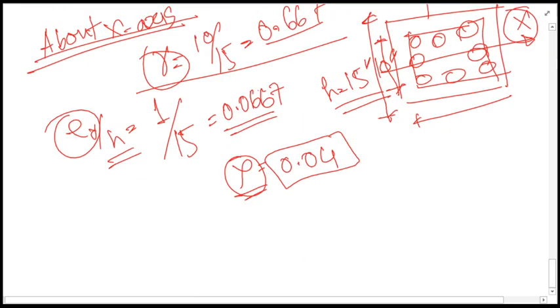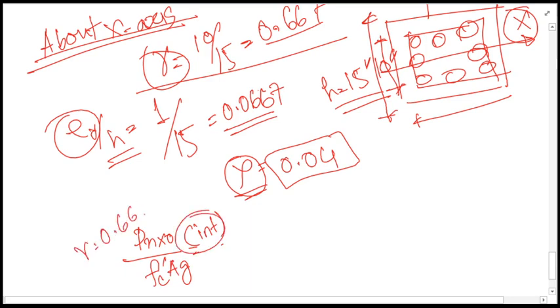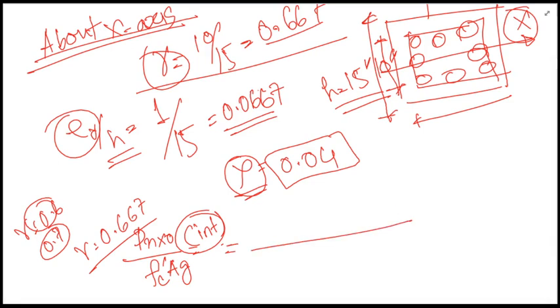Now we'll be calculating, using these two, the capacity in the x-axis, that is Pnxo divided by Fc prime Ag. You will be getting it from the similar chart. We'll be again interpolating this to get gamma equals 0.667, as we don't have a 0.667 graph directly; we have 0.6 and 0.7. So from these two graphs again we'll be calculating this. Let's see what we get from the two different graphs.